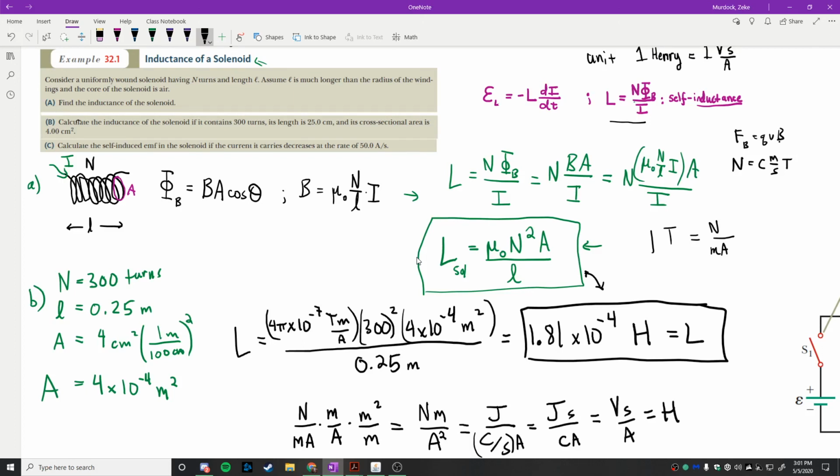So what could we have done to make the inductance of the solenoid larger? What do you guys notice? Yeah, the number of loops. That's the biggest thing you could have done, right? Just make it have more loops. When we talk about inductance, we say that these things have an inductance. But often you're trying to put something like this in a circuit, and you call it an inductor. An inductor basically is really dependent on the number of coils within the system. Coils matter, also the area matters, the shorter it is matters as well.